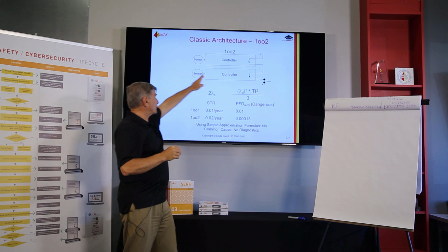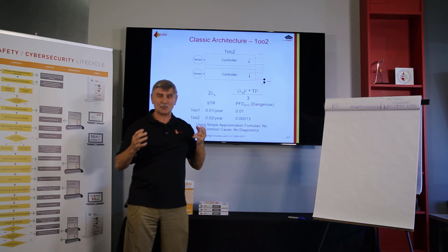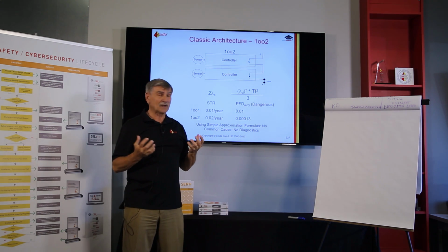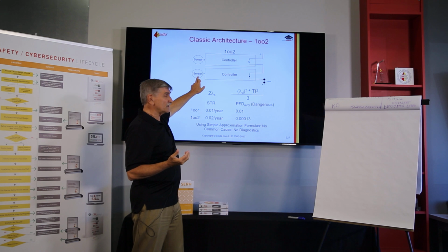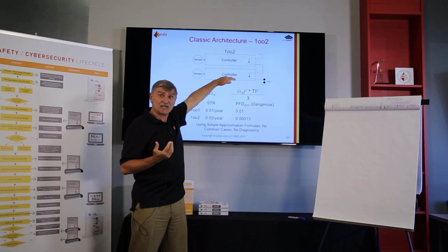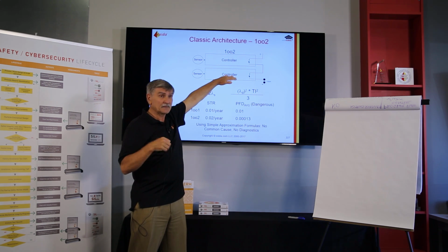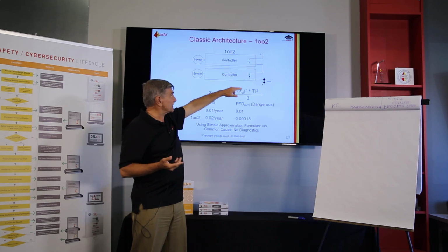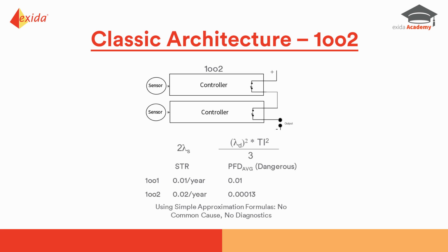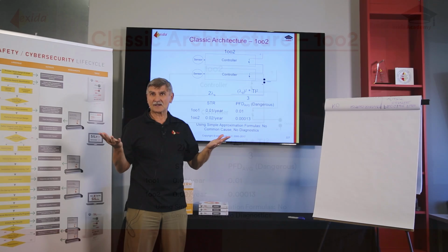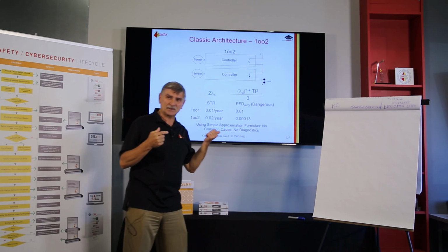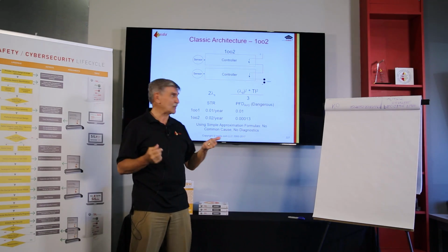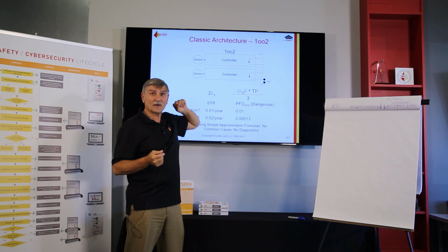The circuitry driving the switch may not allow the switch to open, but the bottom line is if there's a dangerous condition and one of these systems has failed dangerously, the system in a 1 out of 1 will fail dangerously, but here I have another one, and it's wired in series so it can de-energize the output. Make sense? Only one of the switches has to de-energize the output. That's why we call it 1 out of 2.